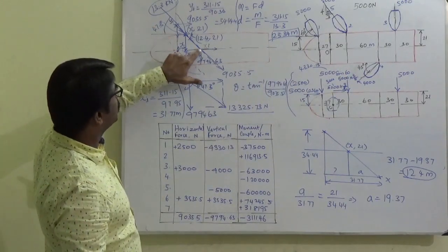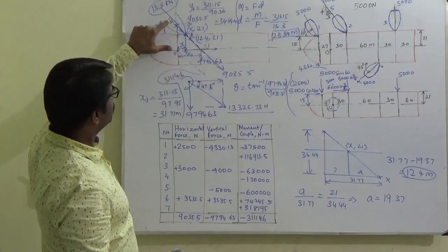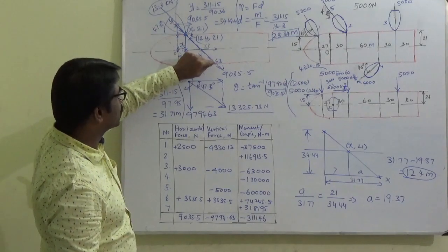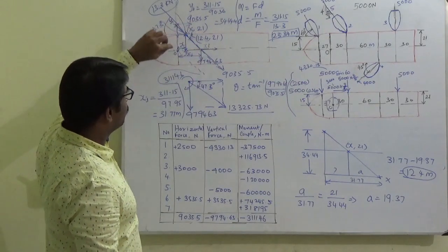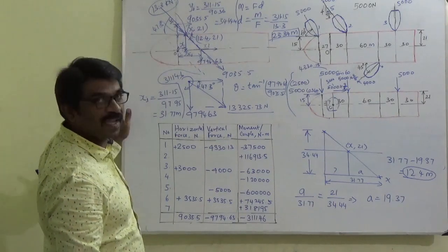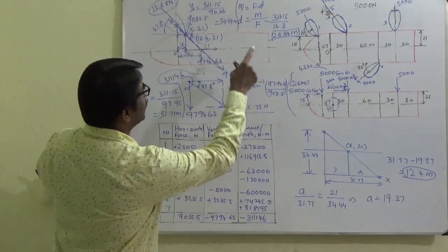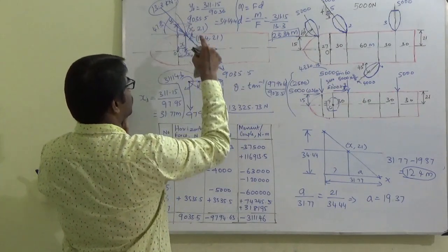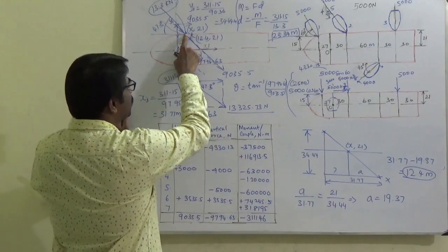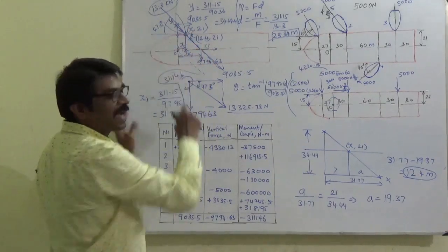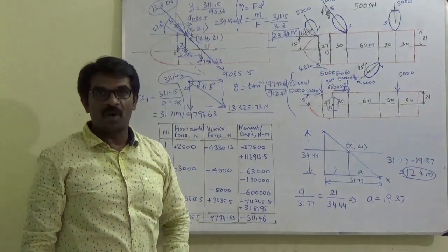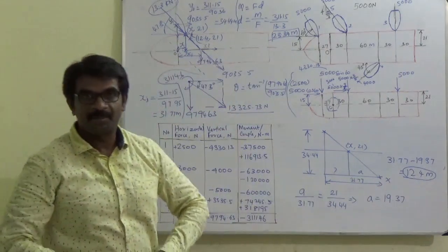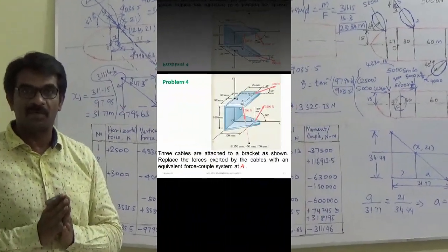For that, we have found the x-intercept, the y-intercept of the line of action of the force. How do we obtain the line of action of the force? We release the couple from this point, so we shifted the force away, finding out the distance d. Okay, this is the distance. Then finding out y-intercept and x-intercept to find out the x point on the hull, because we know the y point, right? That distance is 12.4 meter. I hope this is clear now.